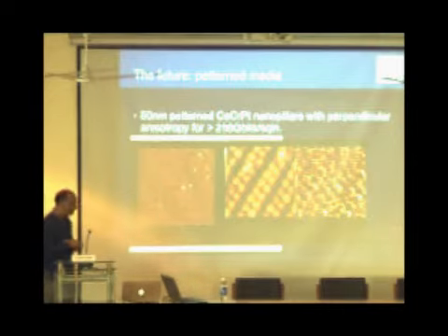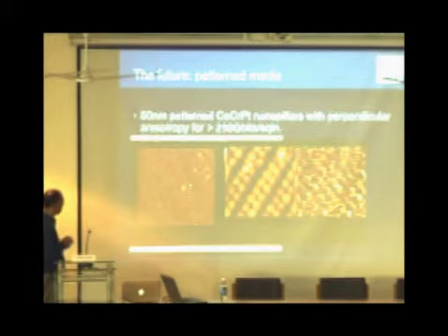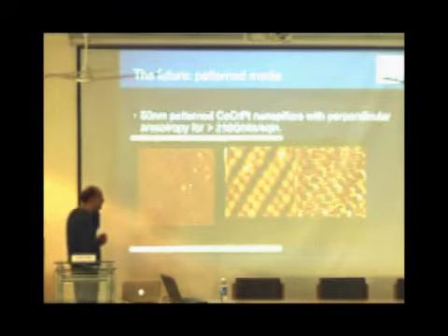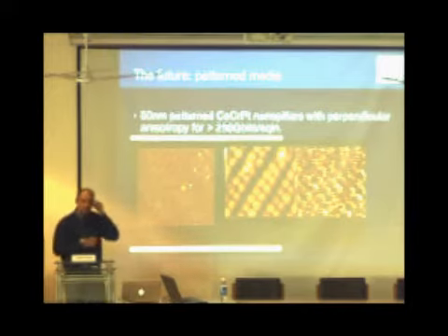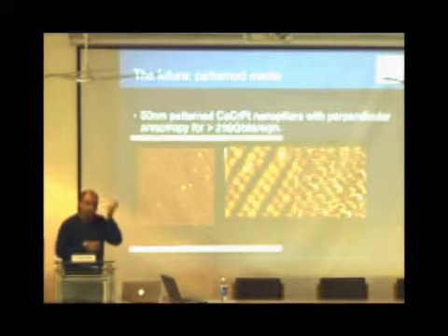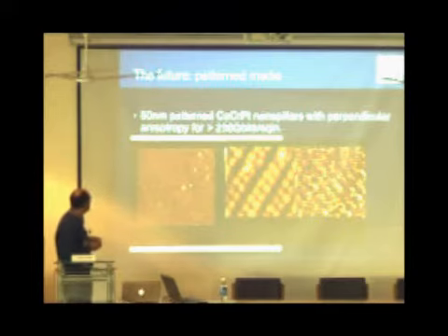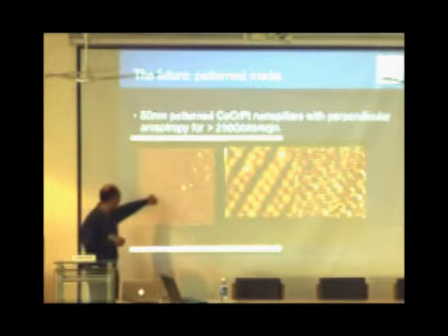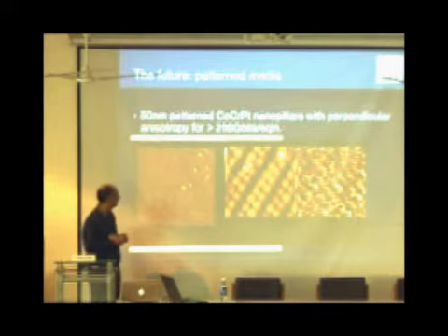So this picture is essentially about how the hard disk drive medium will scale further. When you go above 250 gigabits per square inch, you can't use continuous media for either perpendicular or parallel kind of storage. You have to go to patterned media. So each of these is a nanomagnet, which is essentially a pillar of cobalt chrome.